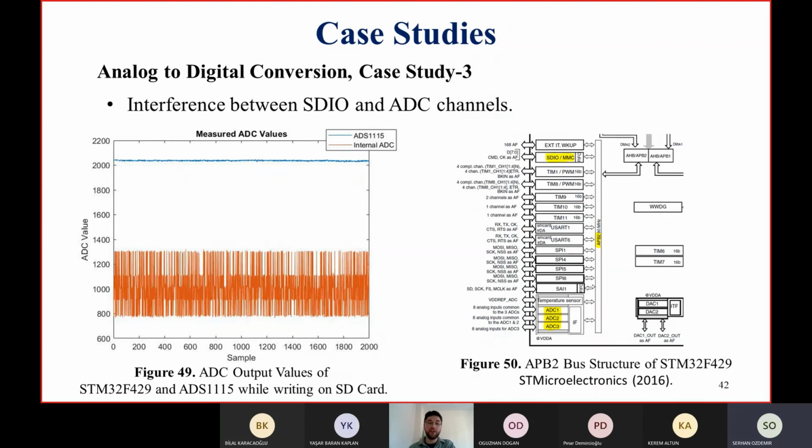First of all, if you have to make very precise analog digital conversions, you have to use an external ADC, or standalone ADCs. Or you have to convert your analog signal while there is no CPU activity at the same time.